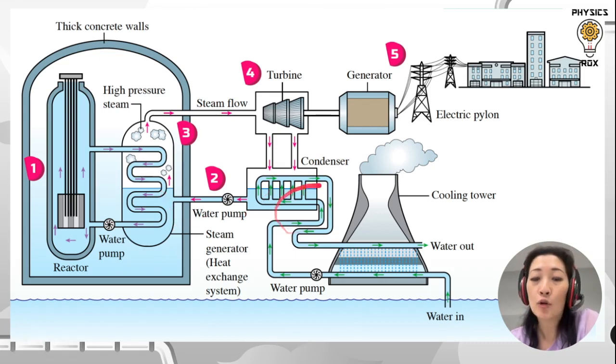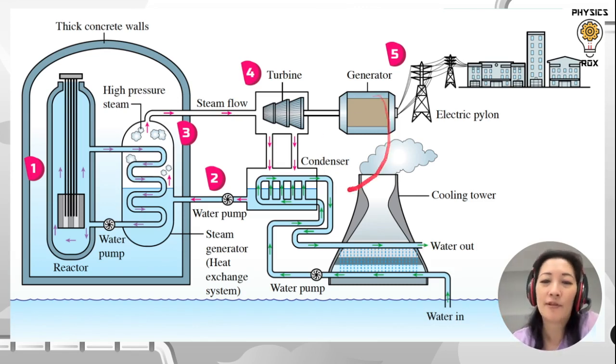So this is the cooling system. Another set of pipes, as you can see. There's another heat exchange going on here. The water inside the pipes will absorb the heat from the water on the outside. The water flows inside the pipe and is taken outside to the environment, released so that the heat is left and escaping out to the environment. That's why we've got a cooling tower over here.